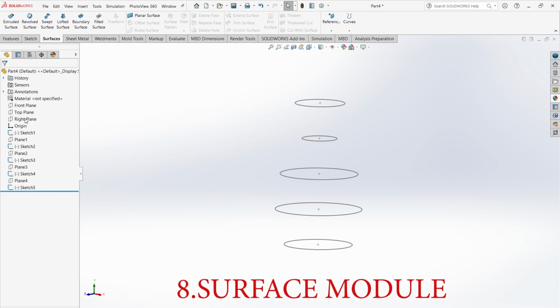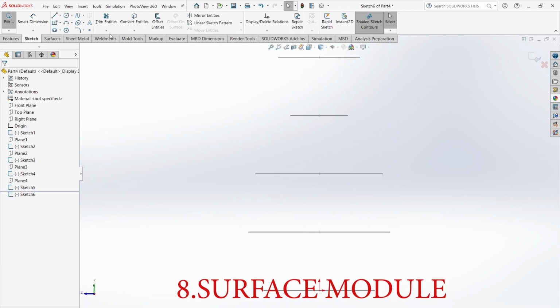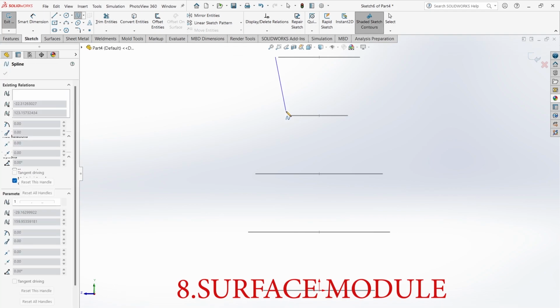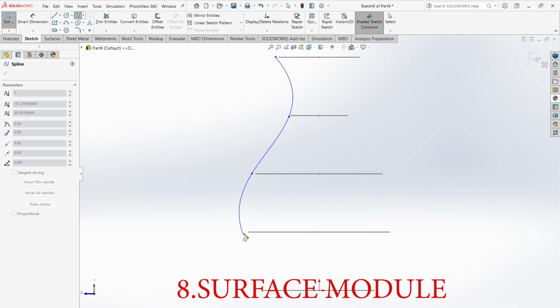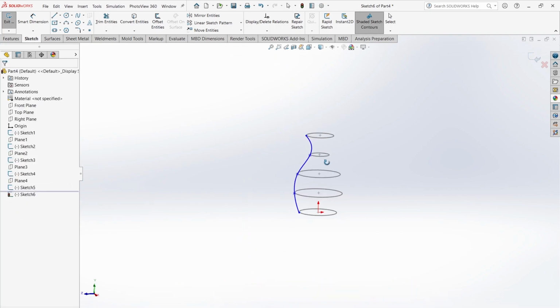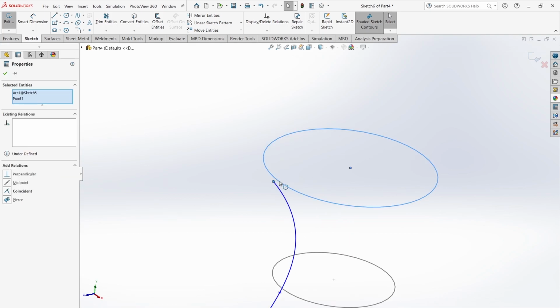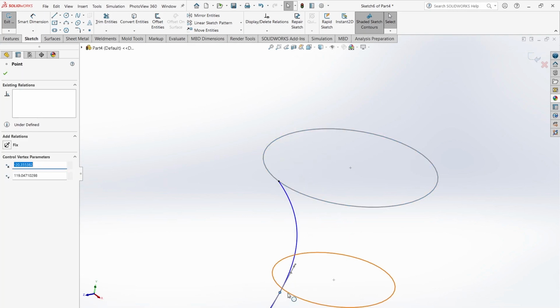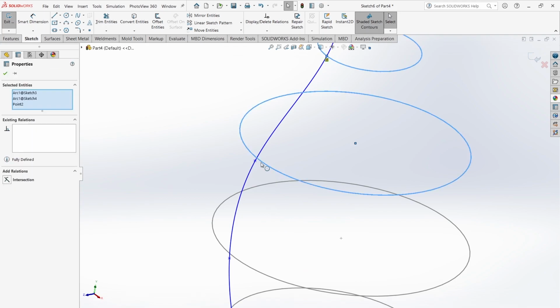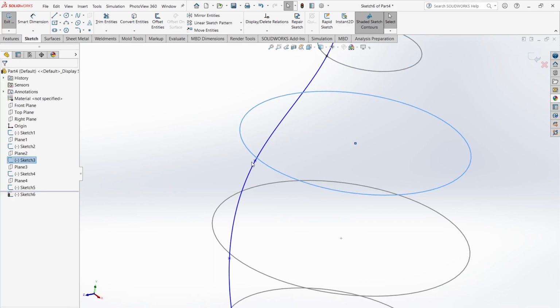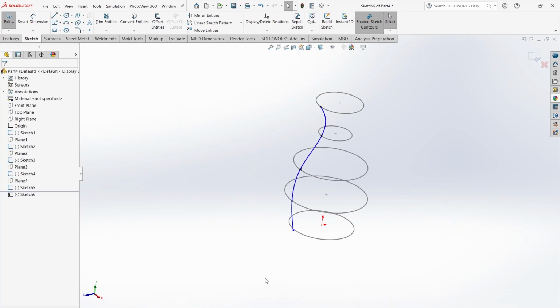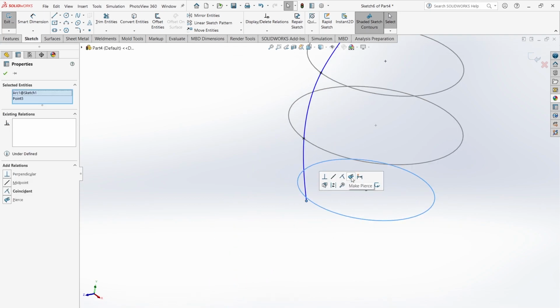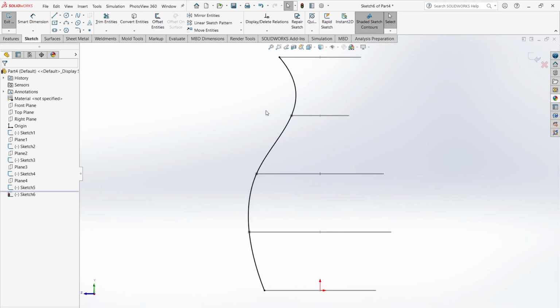Now if I have a guide curve, I'll take right plane sketch. Okay. So this is a spline tool, spline lines. So I will just draw by reference. The very important thing is to make this coincident or pierce. Okay. So this point pierce with this point pierce with this point pierce with this point pierce with this. Okay. Then control H for normal view.